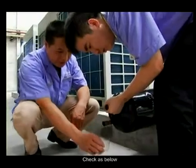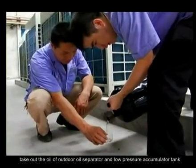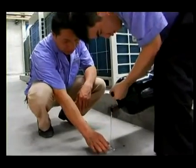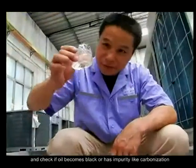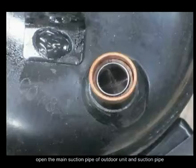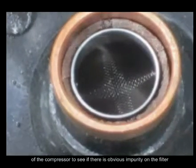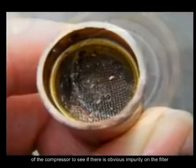Check as below. Take out the oil of the outdoor oil separator and low pressure accumulator tank and check if the oil becomes black or has impurity like carbonization. Open the main suction pipe of the outdoor unit and the suction pipe of the compressor to see if there is obvious impurity on the filter.